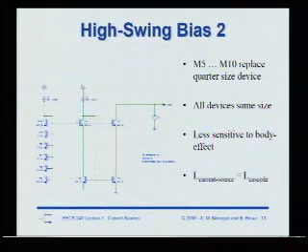So all you want is that margin over temperature and process shouldn't drive transistor M1 into triode region. And because you're deriving your overdrive voltages from like transistors, they're going to track very well with process and temperature. So you're designing a circuit that has inherently good process temperature variability because you have this built-in margin. You don't need to hit that voltage within a few millivolts, right? You're going to hit it within tens of millivolts, maybe even hundreds of millivolts. Okay, we'll stop there.